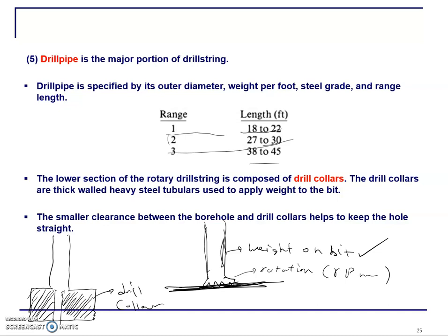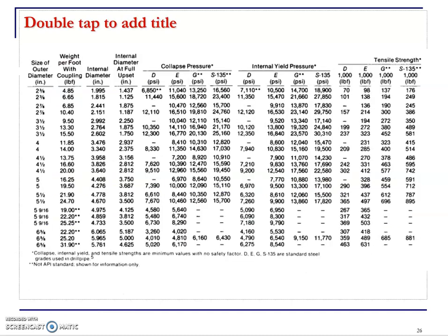So this is another part, and this table provides the different types of drill pipes, not the drill collars but the drill pipes. You can see the outer diameter is one of the important parameters, right? That we have weight per feet, sorry. So for example, one specific size, let's say 4.5 inch, could have 3 different weight per feet, right? Depending on the inner diameter, right? So you can see that the inner diameters are different, right?